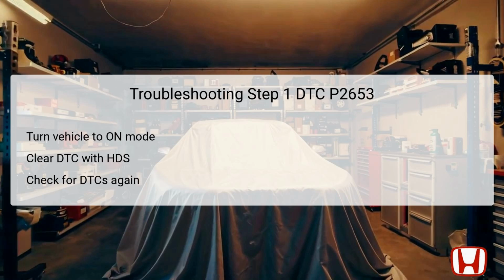P2653 begins with turning the vehicle to the on mode. This step is necessary to power the vehicle's electrical systems and allow for the diagnostic tool, Honda Diagnostic System HDS, to communicate effectively with the vehicle's onboard computer.